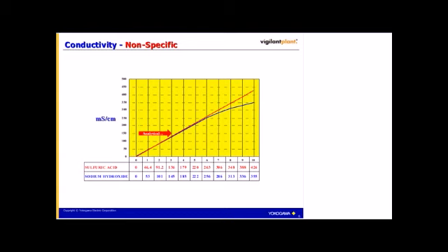So in cases like this, at lower concentration levels, a pH instrument could also be used as an indication telling you whether it happens to be an acid or a base. When you get into higher concentrations, pH is no longer something that you could use, so you have to find another way to know what it is that you're measuring, but you do need to know what's in there.